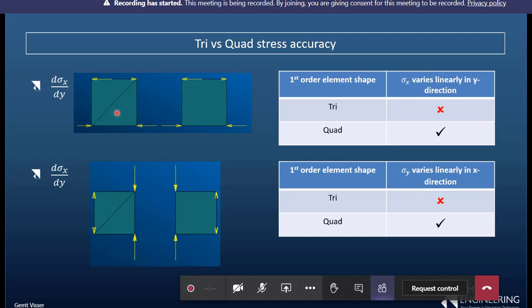So what I typically tell new users in any of the courses I present is the purpose of a tri-3, and by that I mean a tri-3 mesh only, not 1 or 2 tri-3s in a mesh. So the purpose of a tri-3 or a TET4 is either to lose your job, if you're lucky, or to kill somebody with, because it's severely inaccurate.